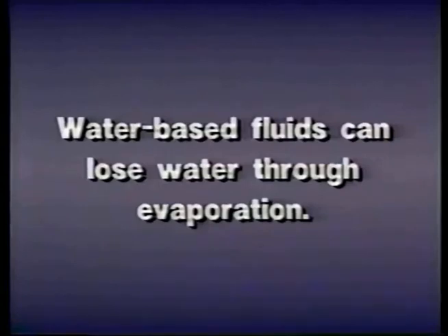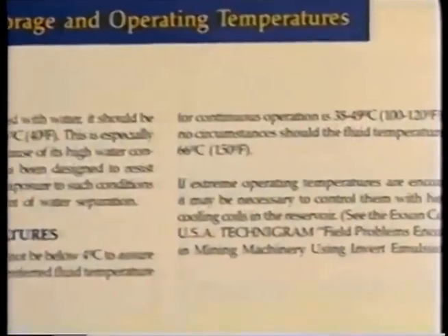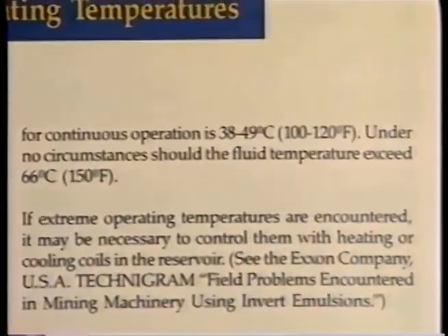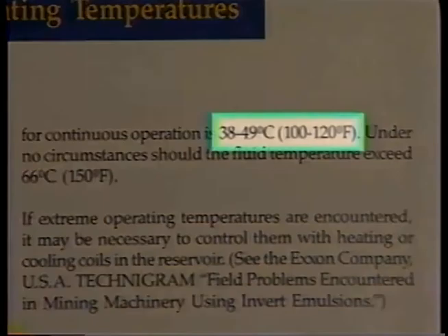A common disadvantage of all water-based fluids is their tendency to lose water through evaporation. That's why most water-based fluids are recommended for use at temperatures below 140 degrees Fahrenheit. 120 degrees is the most common recommended maximum. Water evaporation from these fluids can cause several problems.